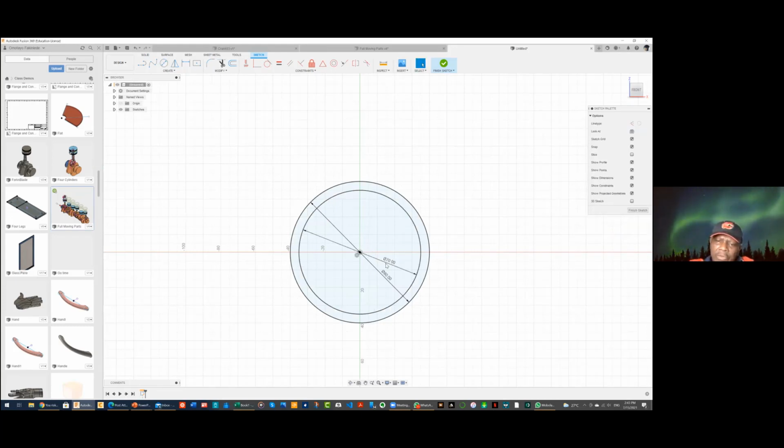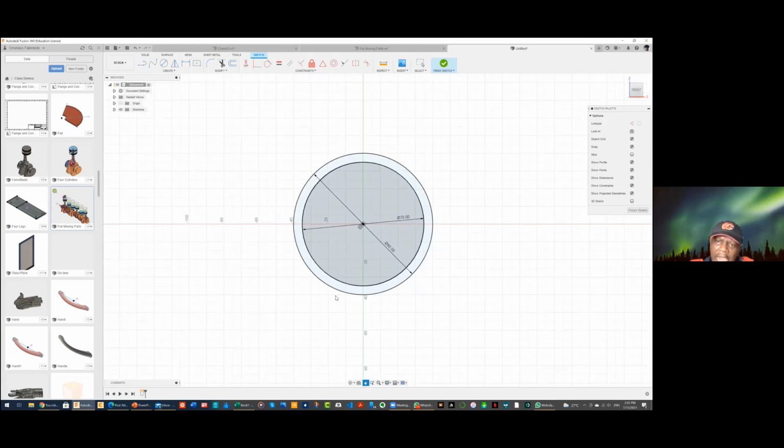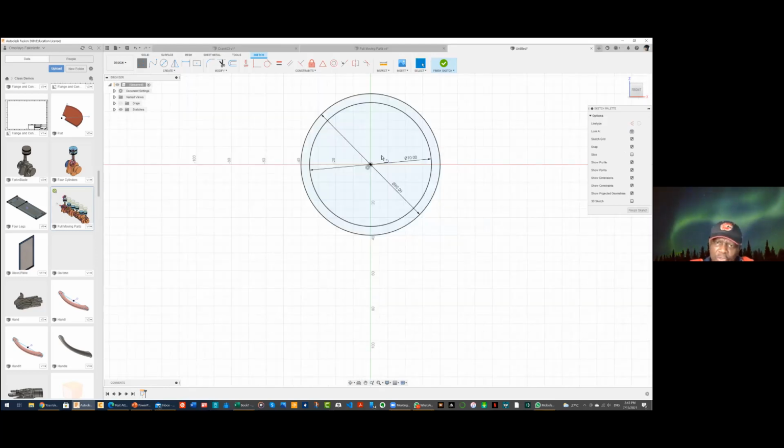Easy. You can move this up. And one thing you might want to do is to create a vertical line here. Create a vertical line, and you will see that it is vertical because of this vertical constraint. If you don't see that vertical constraint, you can apply it. Let me do that again. Control Z removes that. If you want to create a vertical line, to be sure you are doing it accurately, deliberately make sure the line is not vertical. So this is a line.